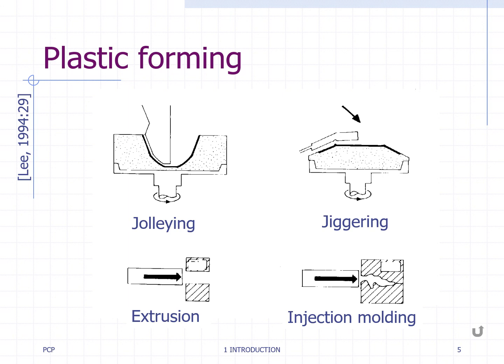Alternatively, we have either extrusion or injection molding. These are multi-material shaping processes, which might be familiar to you from polymers processing. In the case of extrusion, we have as a final product a piece with a fixed cross-section, such as a rectangular brick or a circular tube, for instance.